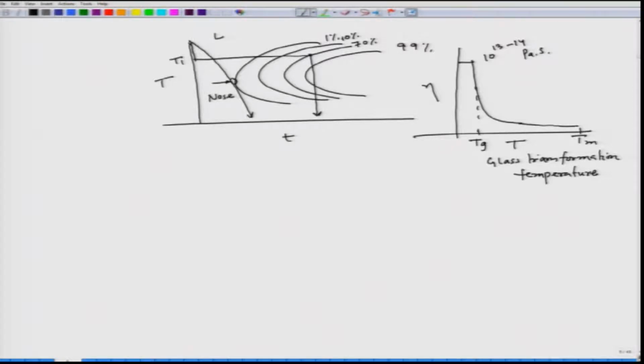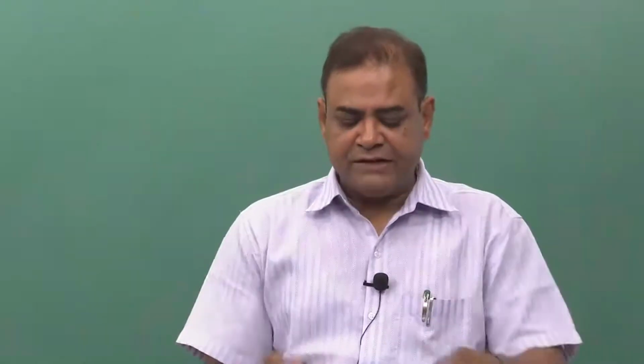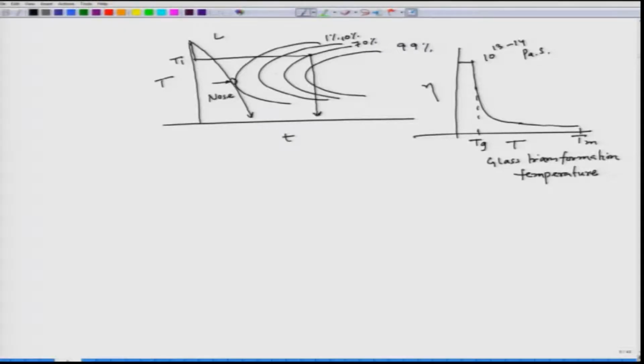So, that way one can make it by doing that heat treatment sequence. That means this is the temperature, let us say T1, and this is the time axis, that means this is my time duration. This much time I have to let lapse at T1, and then I have to quench.